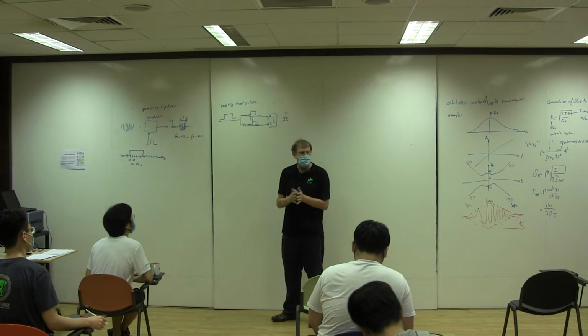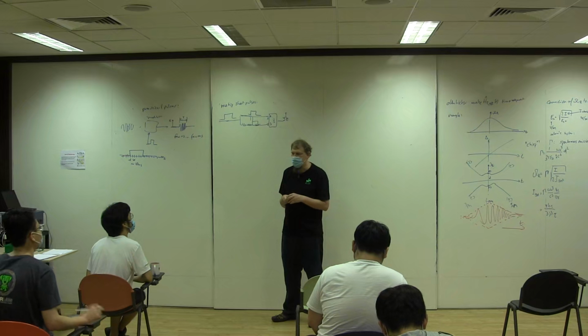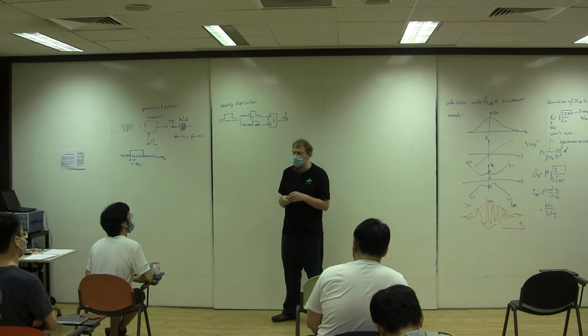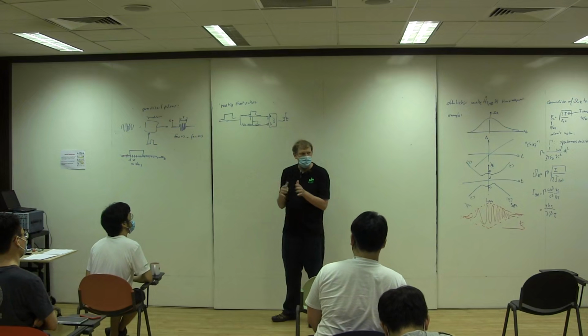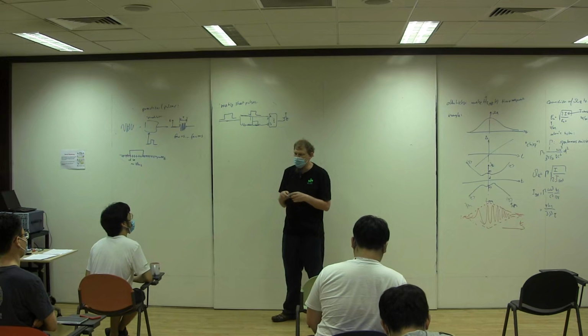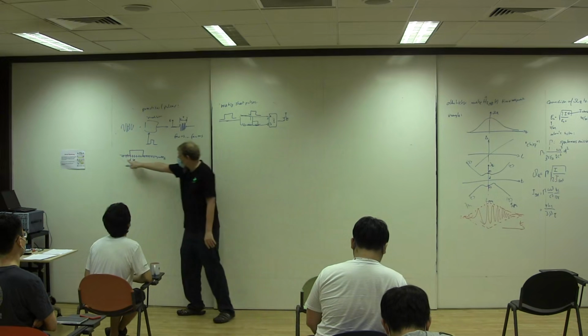So in that sense, you can push the resolution of the timing maybe by a factor of 10 or 20 simply by using these techniques. Okay, so if you need high timing accuracy, look for devices that have a serializer or deserializer built in to make a lot of different pulses that here I've drawn in there.